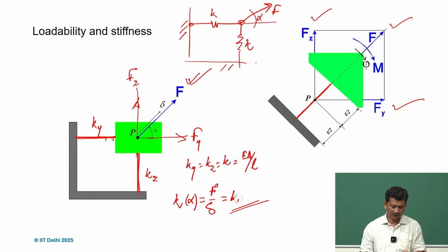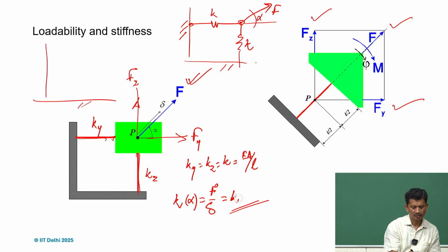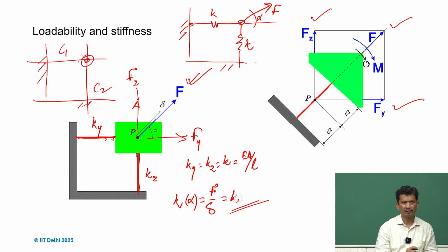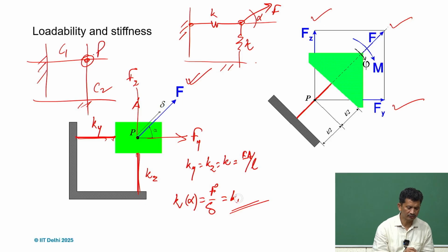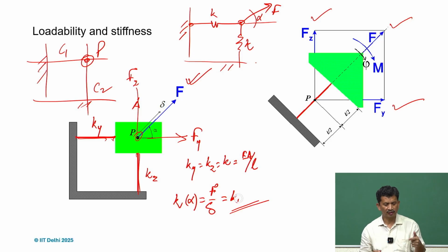So in this case, if we remember what we discussed during controlling degrees of freedom, these are two constraints. So one constraint C1 and one constraint C2, then this is the axis of rotation. And from there we also know that because these two are intersecting at point P, P will be the instantaneous center of rotation.